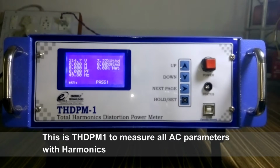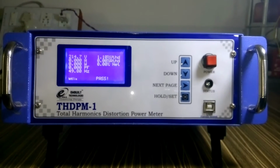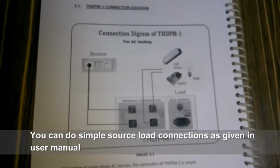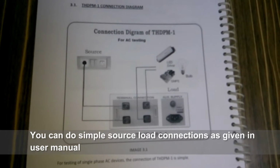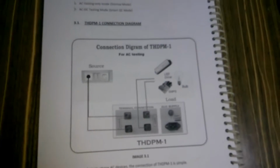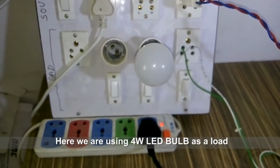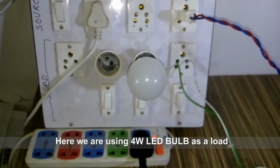So THDPM1 is a single phase energy analyzer showing you all the electrical parameters plus THD of voltage and current. You can see the source load connection, which we can see in the user manual. Two wires are coming in and two wires are going out. This is the source load connection. Here we are using a 4 watt LED bulb as a load and giving this demonstration.